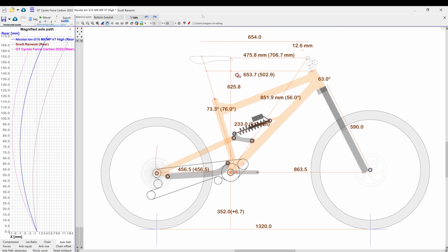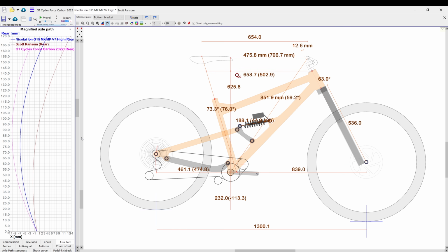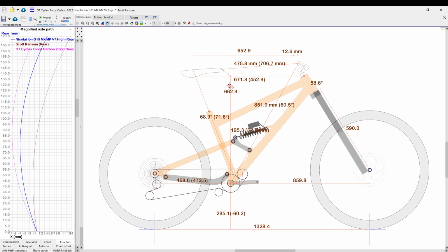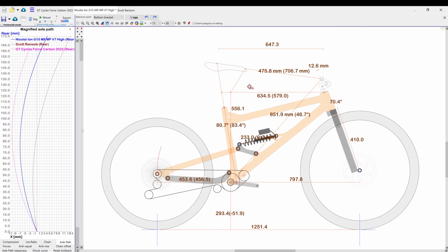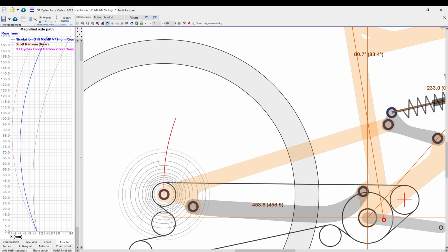I raised this point on a recent post on Instagram, but looking at the static geometry only tells part of the story. All diagrams on manufacturer websites are based on a completely fixed mainframe, and that's not how a bike actually behaves on the trail. In motion, the rear triangle rotates through its travel, and the axle doesn't simply follow the clean curve shown on a static chart. It changes direction as it moves.